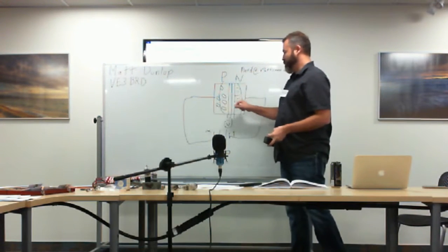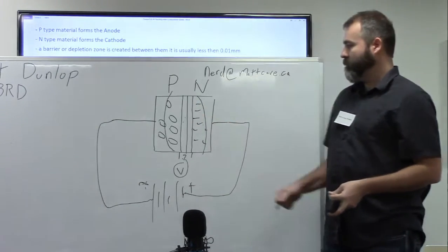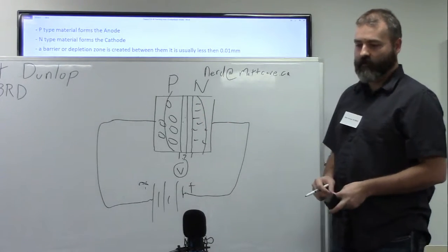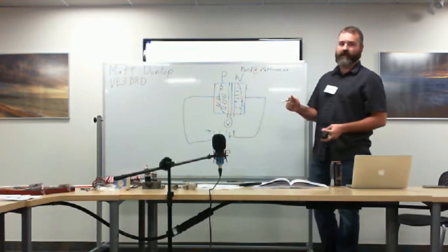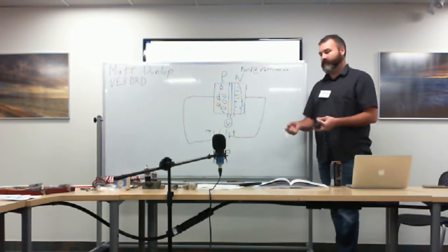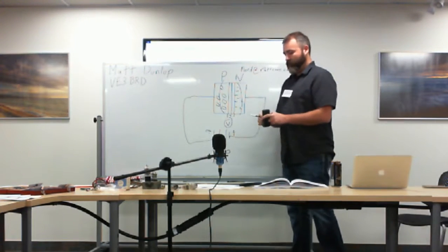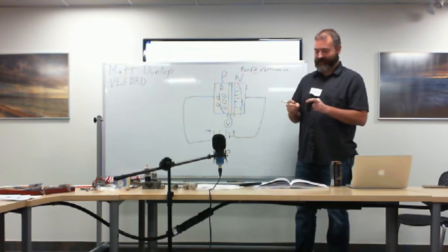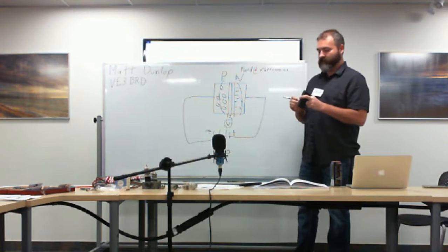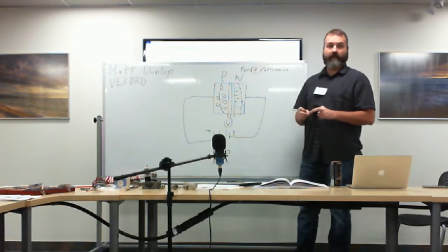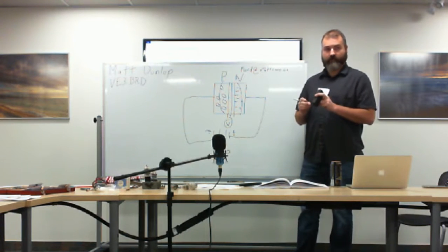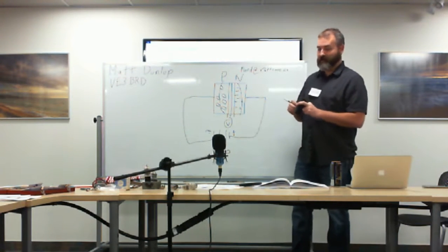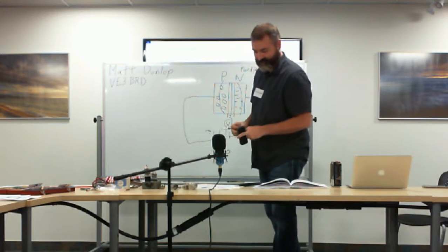They have a lot of extra doping material in their P and N junctions, and they allow the current to flow in the opposite direction if you overcome a certain voltage level. So we don't need to get into the detail of that, but you need to remember that for the test. A Zener diode, because of that property, can be used to be a power regulator in itself for small currents. So they will ask you that question on the test, guaranteed.